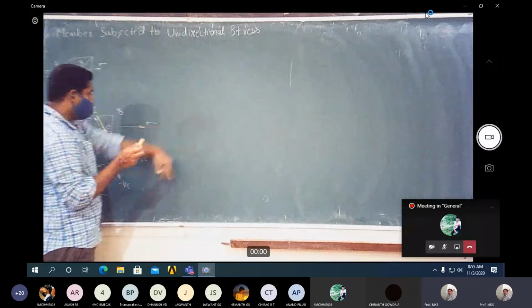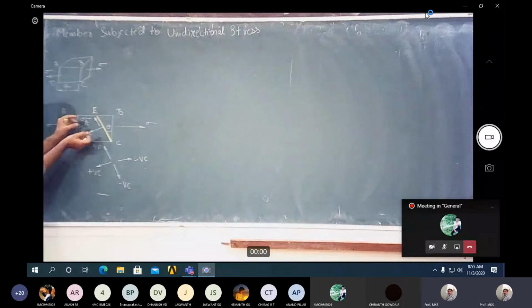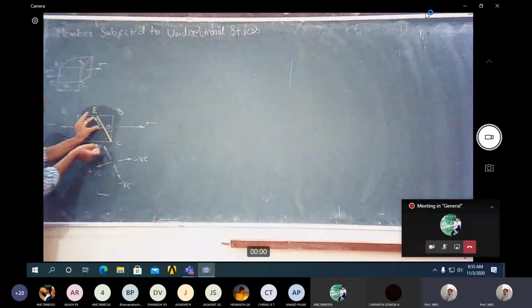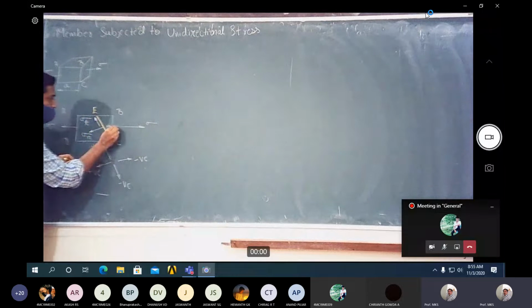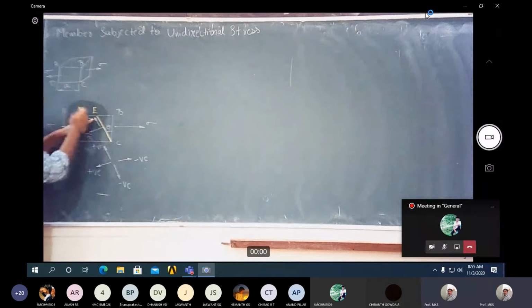So let me resolve this stress acting with respect to the inclined plane, that is, normal stress and tangential stress. So this is the tangential stress. I'll take this along this initial point. It is going upwards.